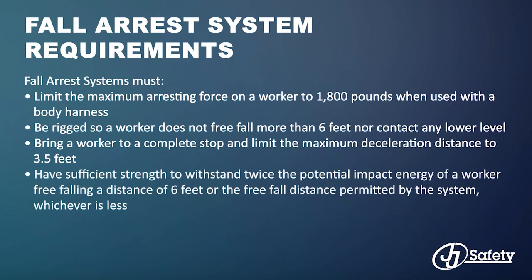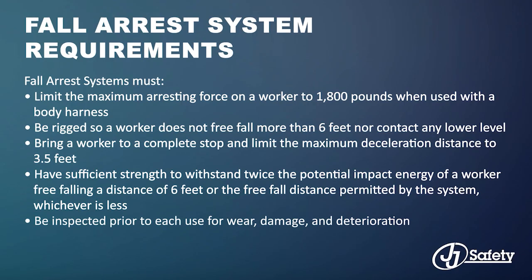Have sufficient strength to withstand twice the potential impact energy of a worker free falling a distance of 6 feet or the free fall distance permitted by the system, whichever is less. Be inspected prior to each use for wear, damage, and deterioration, and remove defective components from service.